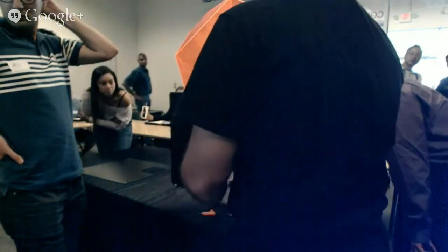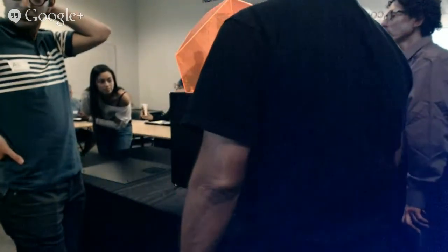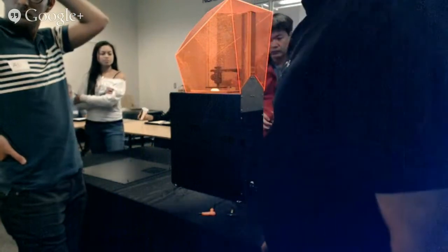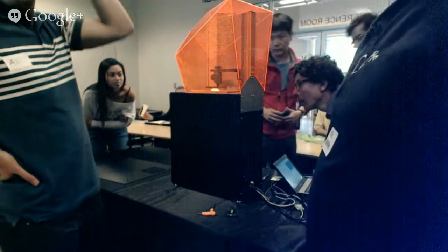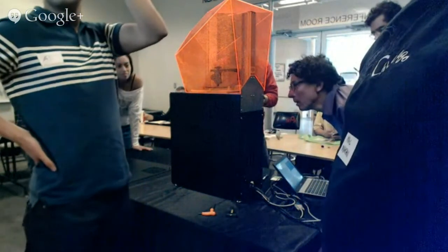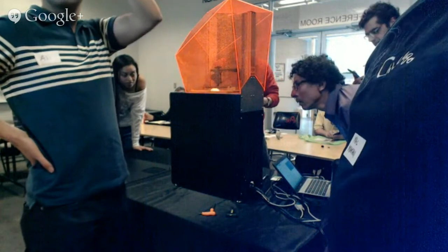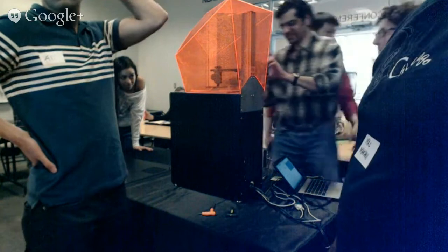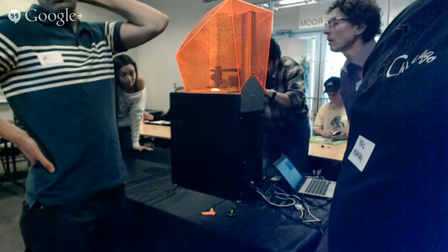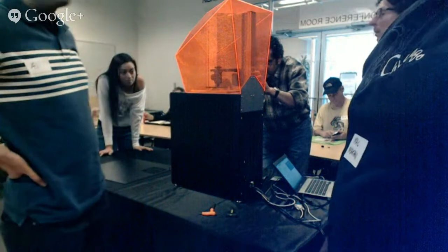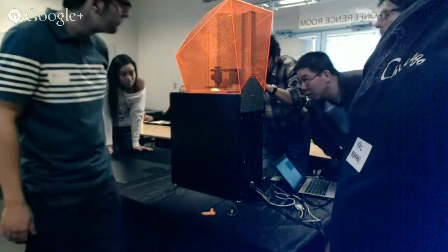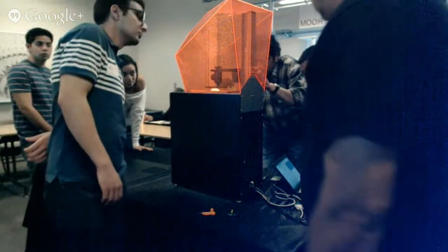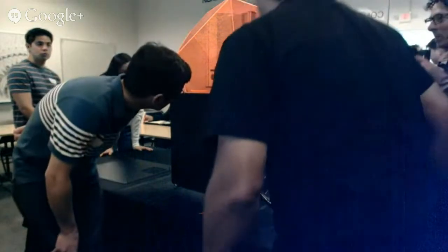Did you make a mold? I didn't make that one. But yeah, this was done, what John said, with vulcanization. That means they printed this part in positive, this shape, and then you sandwich it between 2 pieces of rubber, clamp the rubber, put it into the oven for a couple of hours, and then the impression is in the rubber. So you made a mold out of it, and then this was cast in that rubber mold. That's right. Took the 3D printed part out, and then you put it back together, and you poured metal in. Yeah.